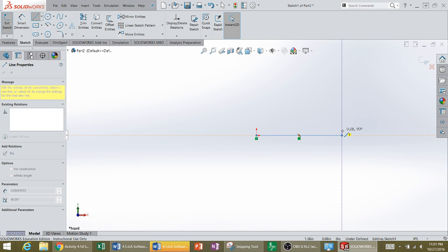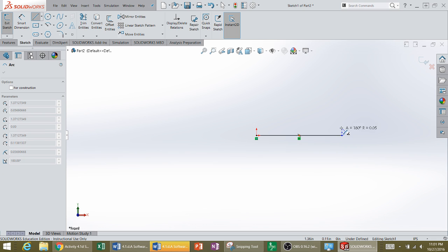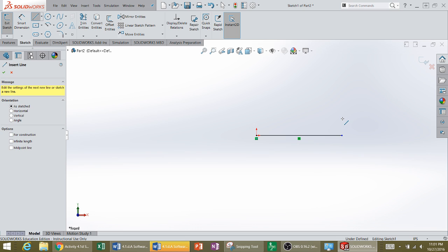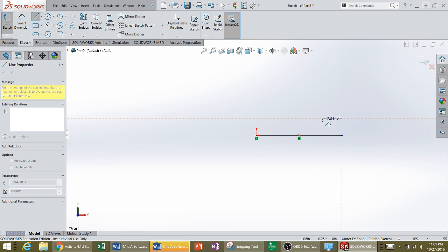Now I'm going to start sketching up. Now you see how I get these yellow lines that appear at 90 degrees? Kind of neat. I just did something there where I came back and touched a line. I didn't want to do that. But I now want to go straight up, and you'll notice that that glyph shows a vertical line. I can click and release, and I get a new line.